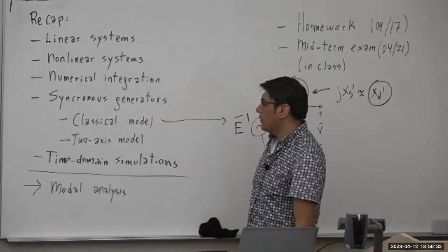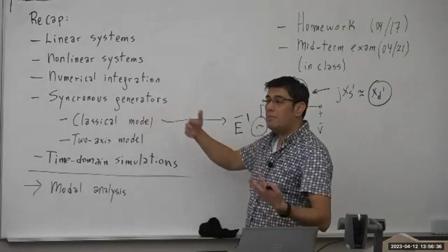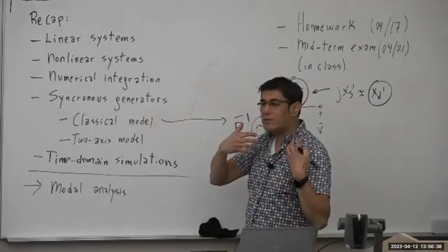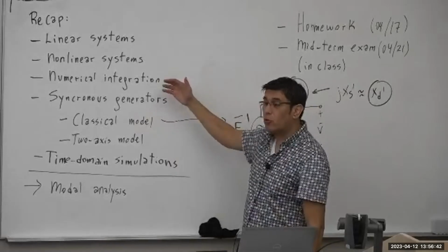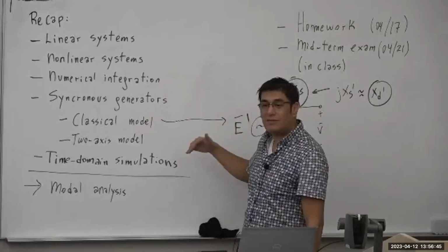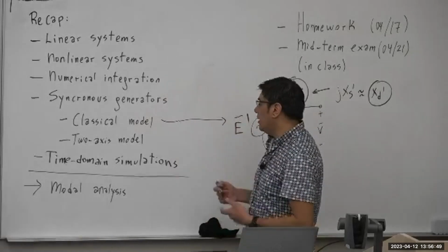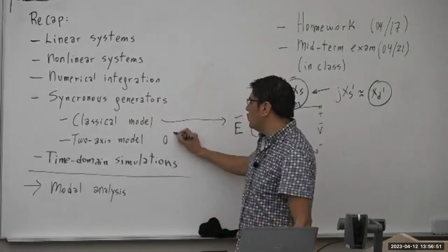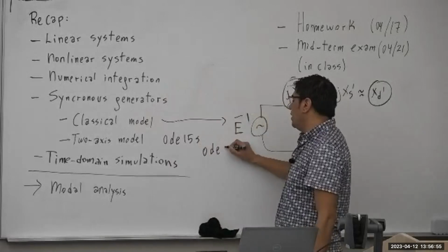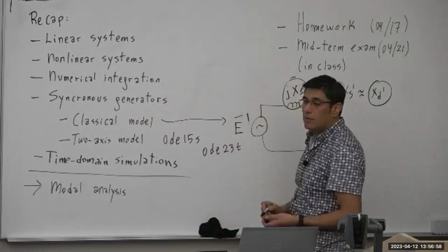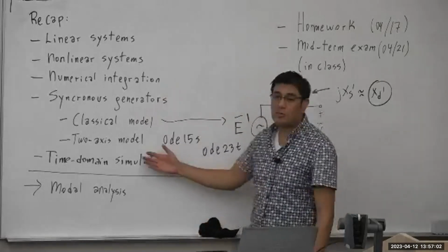The last part we did, just coding. We used MATLAB. We created our own script. We used the numerical integration techniques from the solver from MATLAB to solve this set of differential algebraic equations. And we use basically two solvers, which is ODE15S, or we can use ODE23T. Those are able to deal with differential algebraic equations. And that's what we did.